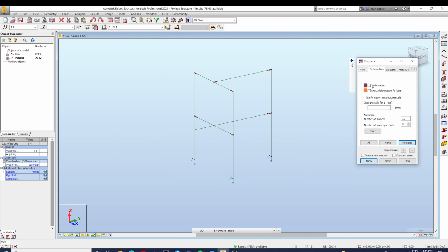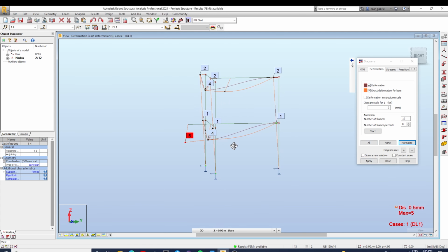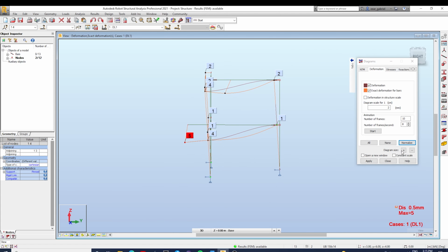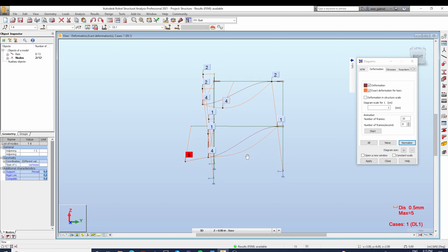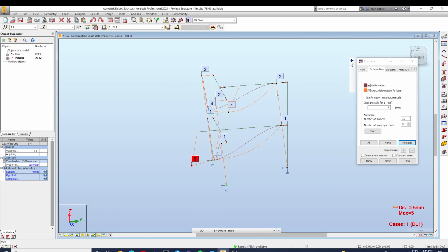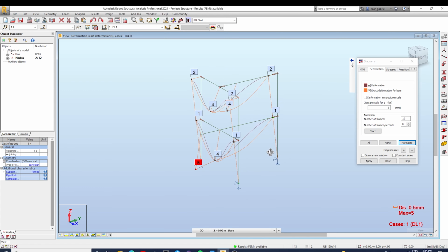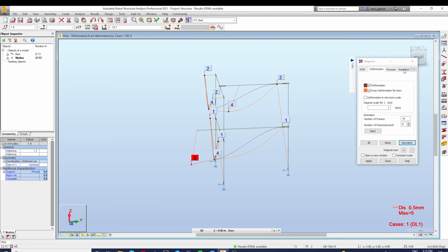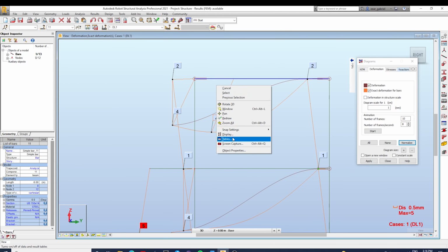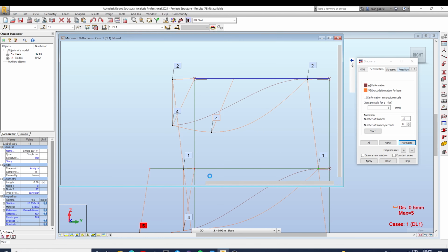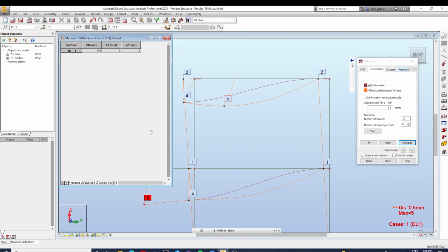Have a look at the deflections as we did in the beginning of the video. Is this displacement looking as you expected? Do you think the structure will deflect this way when under loads? If not, something in the model might be wrong and you need to fix that before going ahead. Check the bar deflections so you can assess the code deflection limits.